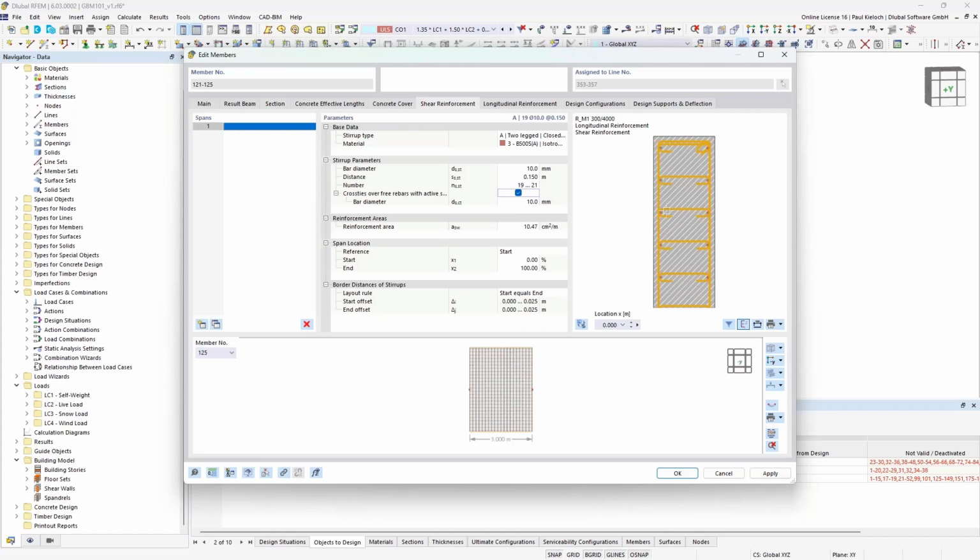So for example, you can go through here and just define that you don't want to apply these cross ties on every rebar here. So you can just click in here. It's a little bit of clicking, I think, for this height of the section, but I decided to do it also for this section just to give you a demonstration of how it works.